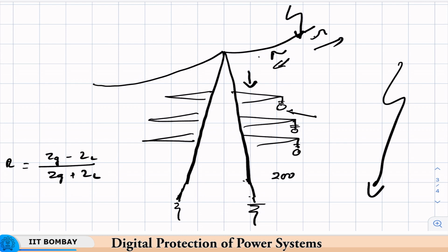grounding resistance, that is why we say that the grounding resistance should be as low as possible, and certainly less than 10 ohms. So, this is what is specified in transmission line specifications. You need the grounding resistance to be less than 10 ohms, and very near to the substation, sometimes it is even specified to be less than 1 ohm. Okay. So, here at this discontinuity point, the reflection coefficient will be Rg minus ZL divided by Rg plus ZL.